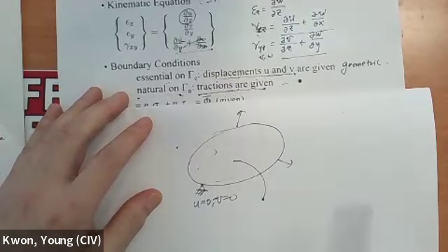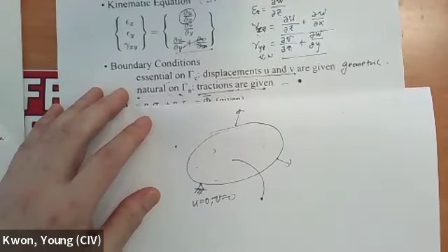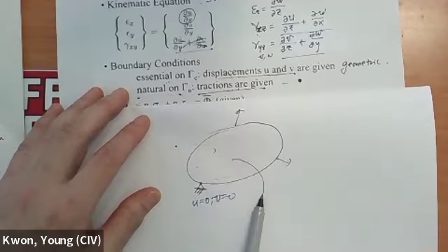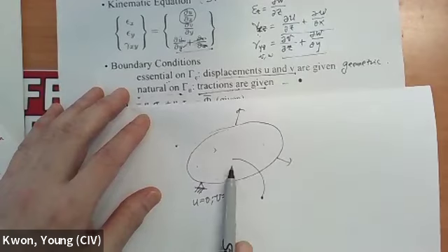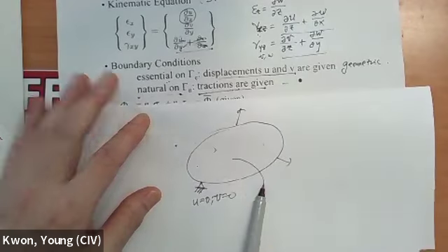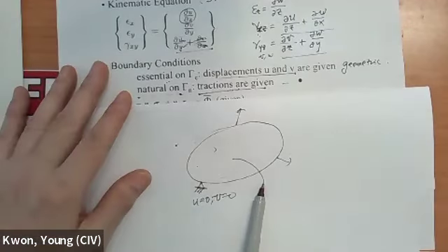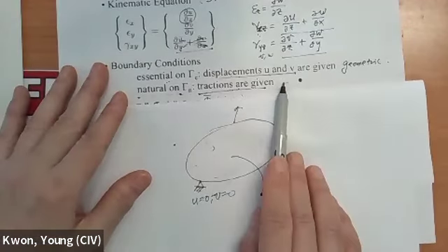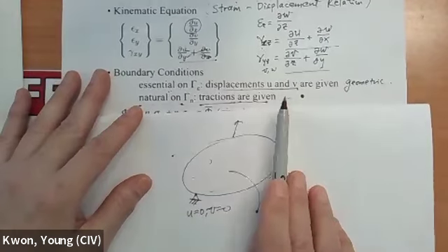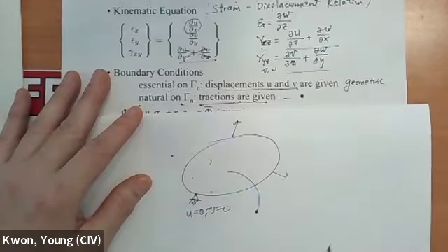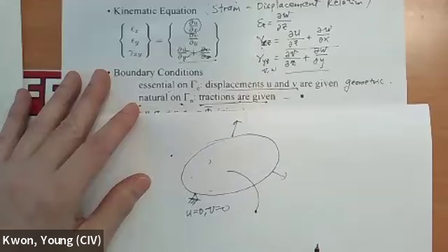Right? A transient problem is different, because in a transient problem we are following the solution as a function of time. So yes, we are going to see rigid body motion as well as deformation, and we are going to follow that as a function of time. So we can still solve the problem, but for a boundary value problem, a static problem, if you have rigid body motion, you cannot find the solution from your matrix.